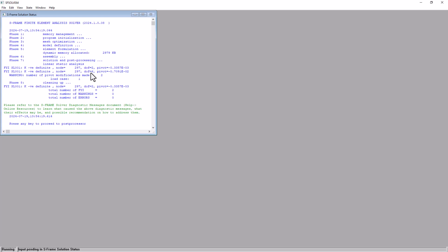I haven't actually shown the loads that I have, but for your information, they're all in the vertical direction, basically the Z-axis. Degree of freedom 2 is indicative of Y translation. Degree of freedom 6 is indicative of rotation about the Z-axis. So these are two directions where I have instabilities, but I don't actually have any loads that would induce any sort of action in that direction. However, it is letting us know for our information that we do have instabilities in those directions.